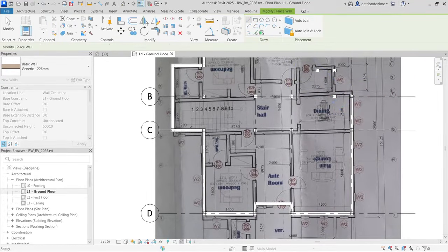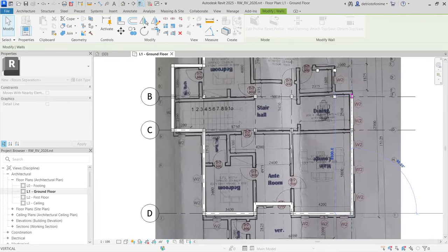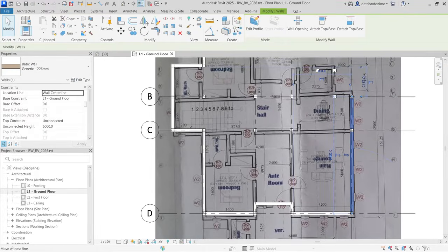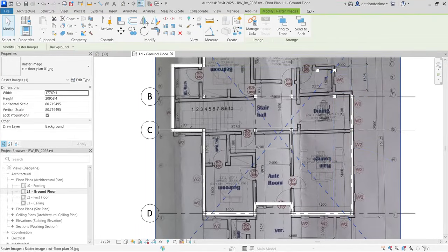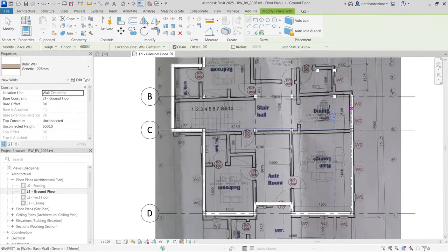Okay, we've made an error in that last part. Go ahead and hit escape twice, and then just drag this wall to the very top or the midpoint of this one. And like we mentioned, you can select the wall that you want, press CS to create similar, and just continue creating the chain of the wall. Go back to the midpoint of this one.